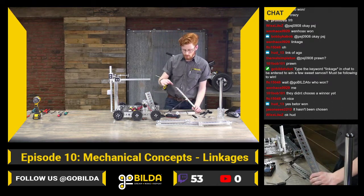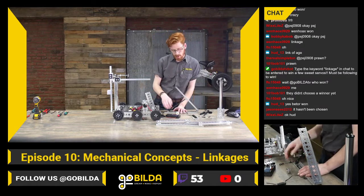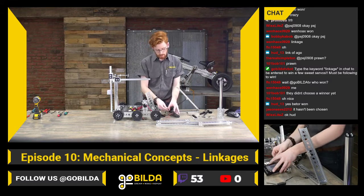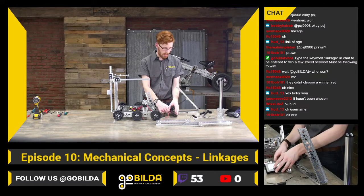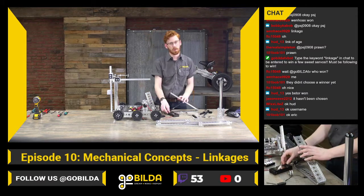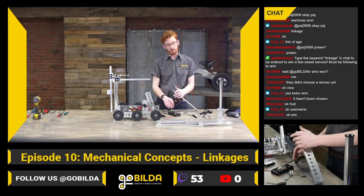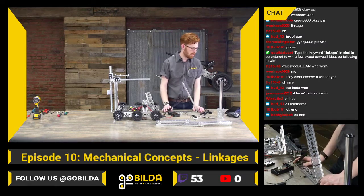So the further out you mount that actuator, the more force you're going to get out of it. In this case, this is the faster of the Hitec Linear Servos that we offer, and it works really well when mounted about this far away, and you get a pretty nice amount of force out of it, especially if you're moving something fairly lightweight.